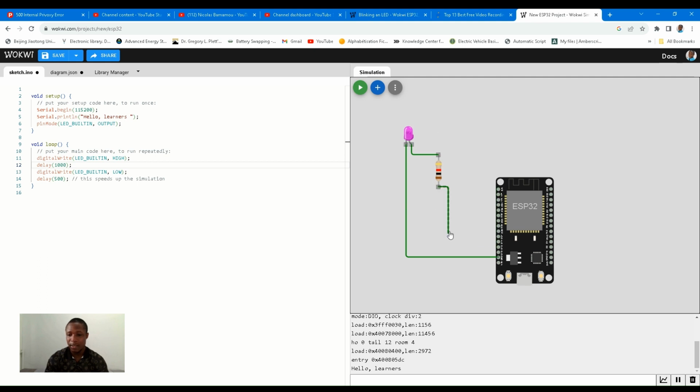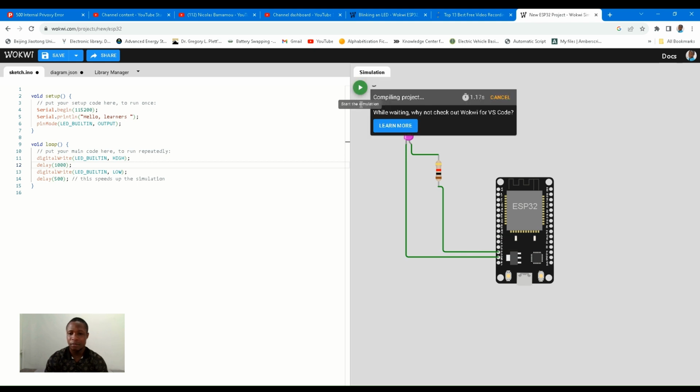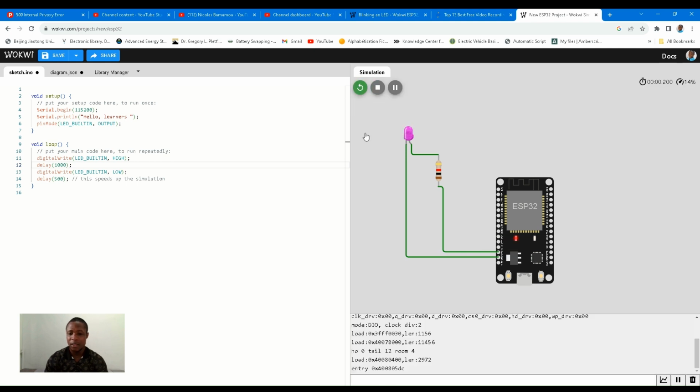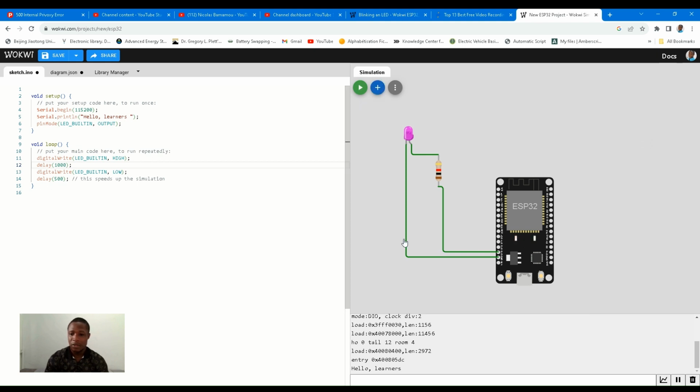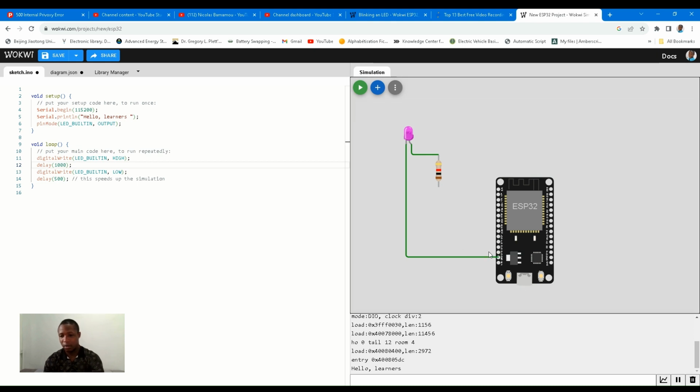Let's say we want to connect this to a pin, let me see which pin we have close. Let's say pin 13. Also, this pin 13 is directly connected to the built-in LED. So if, for example, I run this code, yeah, this built-in LED is connected to pin 2, I think. Yes, so let me connect this to pin 2 and see if I'm correct.